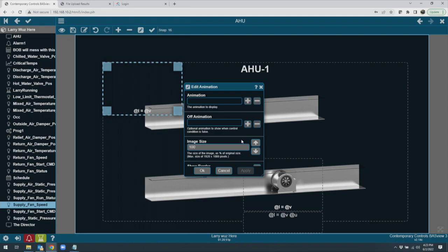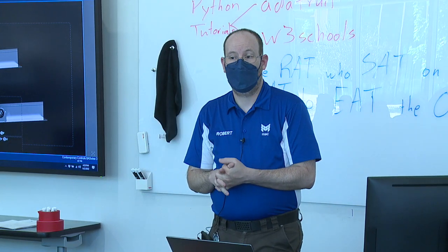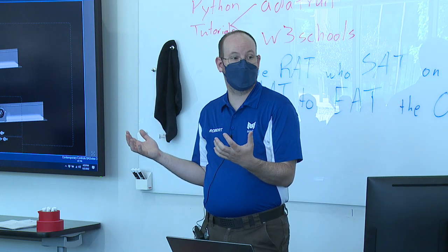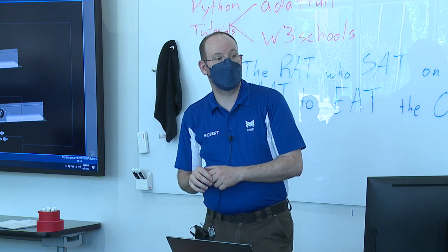So, yes, there are. There are companies that will gladly build you that graphic. There are companies that already have generic graphics built. That is one of two ways the industry currently is doing graphics. In that situation, you have one background image file, and you bring in your animated GIFs and get them lined up exactly on top of things like fans and pumps. Add whatever labels you want, and away you go.